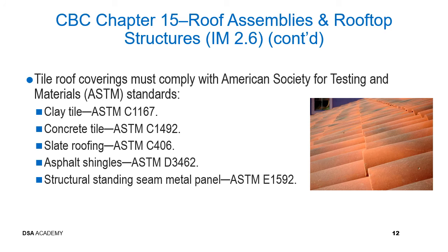Tile roof coverings must comply with American Society for Testing and Materials Standards, ASTM. For example, clay tile, ASTM C1167, concrete tile, ASTM C1492, slate shingle, ASTM C406, asphalt shingles, ASTM D3462, structural standing seam metal panel, ASTM E1592.